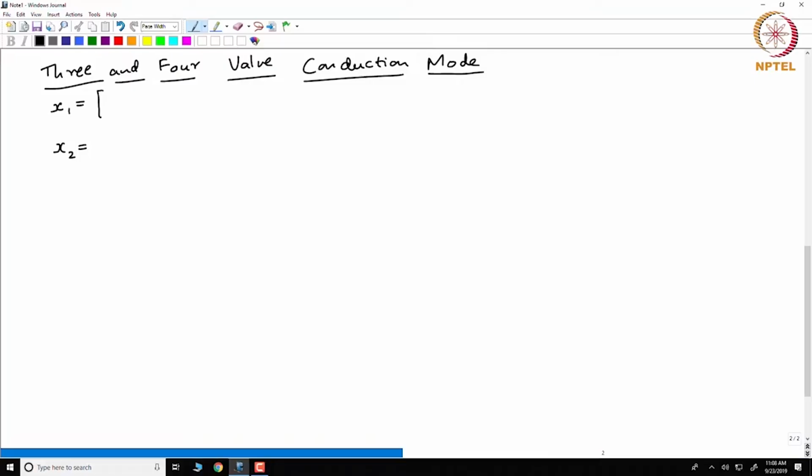See, 4 valves are conducting, but are there 4 state variables? You are familiar with circuit analysis, right? I mean, you do loop analysis, node analysis. Here, we already considered analysis of such circuits. I mean, we did actually loop or mesh analysis. So, how many loops are there? 3 loops, but one of the currents is known.